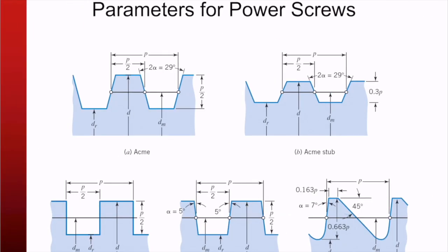All right, now let's go back to this topic of power screws, a screw jack. So jacks, load frames, worm drives, some hydraulic presses maybe, all work with power screws. The most common ones here are the Acme threads. For instance, if you look at the MTS load frame,